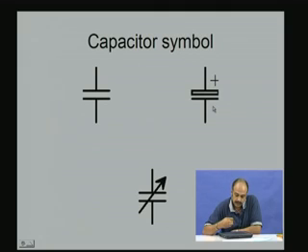And these are the symbols that you normally encounter in the literature, in electric circuits, for the capacitor. This is the most common symbol that you will encounter, two parallel lines with two leads coming out. This is another symbol which is normally used for electrolytic capacitance, one with a thicker rectangular box type terminal, and another terminal which is a line. The box type has a plus there indicating that it is a polarized capacitor, that has to be always positive with respect to the other terminal. And then you can also have variable capacitors with the arrow indicating that it is a variable capacitor.